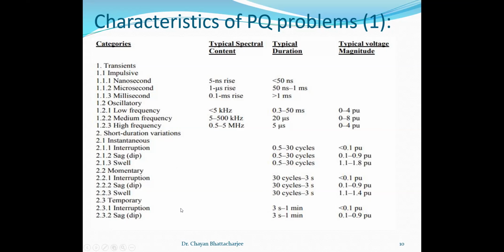Say, for a particular sensitive load, the voltage sag or swell is not that high, but its stay in the system is very long, approximately 1 minute for the sag, swell, or interruption. If that sag lasted only 30 cycles, the sensitive device can withstand it.